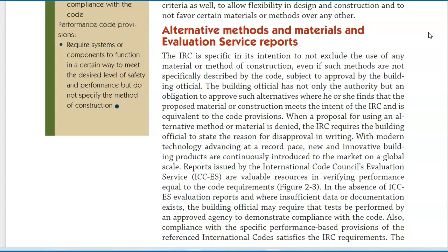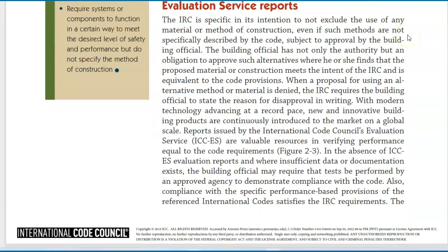In the absence of ICC-ES evaluation reports and where insufficient data or documentation exists, the building official may require that tests be performed by an approved agency to demonstrate compliance with the code. Also, compliance with the specific performance-based provisions of the referenced international code satisfies the IRC requirements.